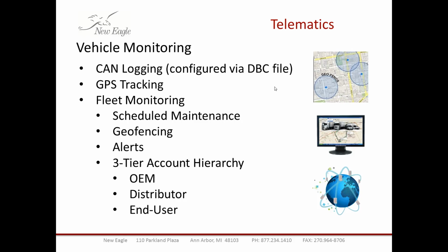Another thing that we can do is set up alerts. If there are thresholds for operating parameters like RPM or coolant temp, or whatever is appropriate for your application, that indicate that a vehicle is either malfunctioning or being used in excess of its rated capacity, you can get an alert so that somebody who needs to can go see what's going on with that vehicle.